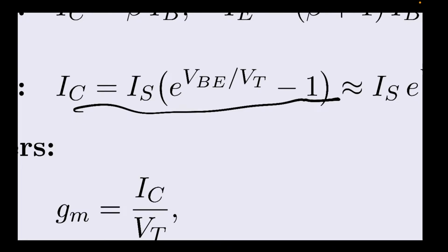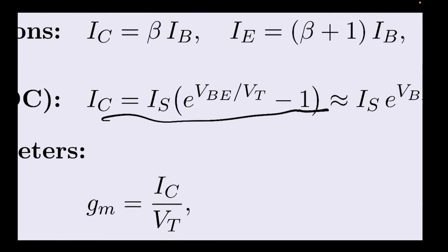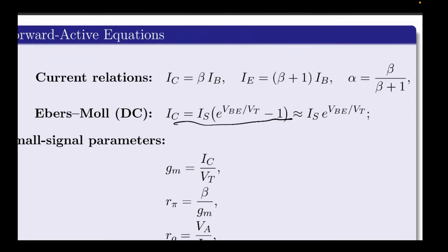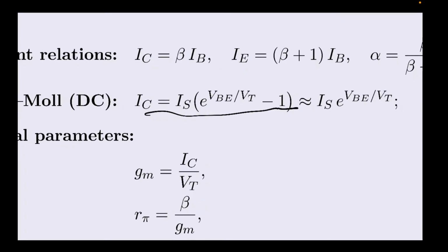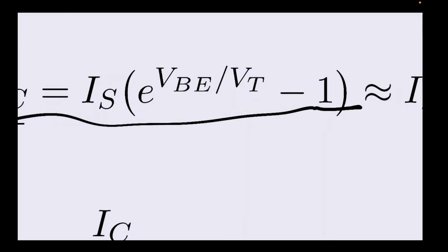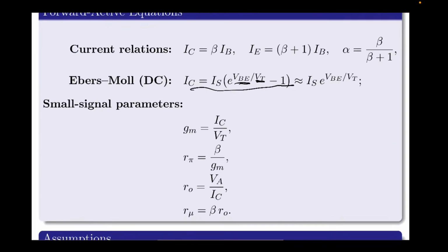This one is actually kind of cool, where you end up being able to derive things. You notice how it doesn't really have much to do with the circuit. We have VBE, the voltage between the base and the emitter, divided by VT, which I'm sure you've all seen as 26 millivolts many times. We're able to derive the collector current. It's just a consequence of the physics.